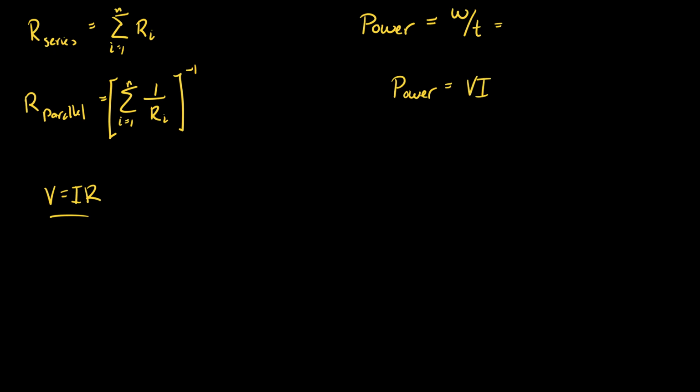And obviously, knowing Ohm's law exists, we also get I squared times R and V squared over R as equivalent ways of calculating the power dissipation. Just like the energy storage in the capacitor had 3 different ways we could calculate the energy storage, we have 3 different ways we can calculate the power dissipation. Oh, and what I was going to write here, this is a joule per second, which is also known as a watt.